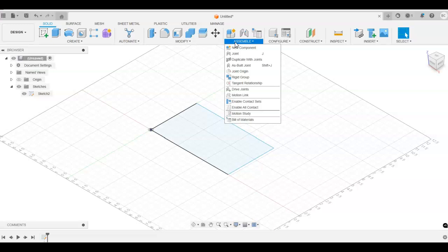We'll go through some of those first before we get into some of the more advanced modeling. What I'm talking about with that is there are two types of modeling when we're designing actual machinery or equipment: top-down design or bottom-up design. I tend to draw parts first and then create them as an assembly, but you could draw your assembly first and then add parts in as you go.